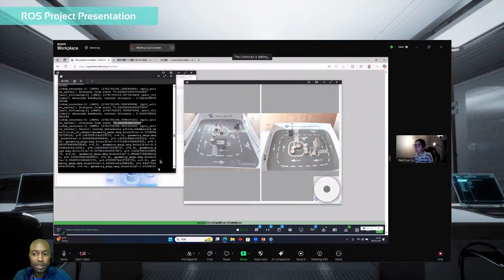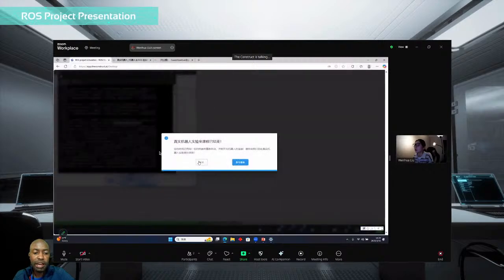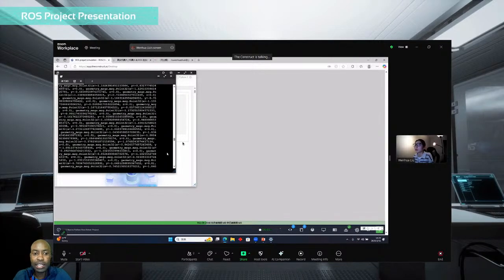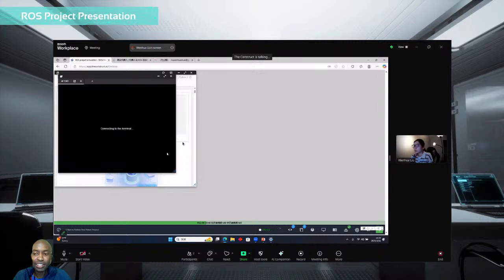If you realize that the distance of your front index is now too short, or you're too close to the wall, then that requires an immediate turn, so your angular velocity is bound to be faster, right? But if the distance is slightly bigger, you can start turning with a less aggressive angular velocity. That's the layered approach I was hinting at, but that's for another time. It's just harder because you have to do everything manually, whereas if you're using some type of proportional controller, it will all be simpler, right?